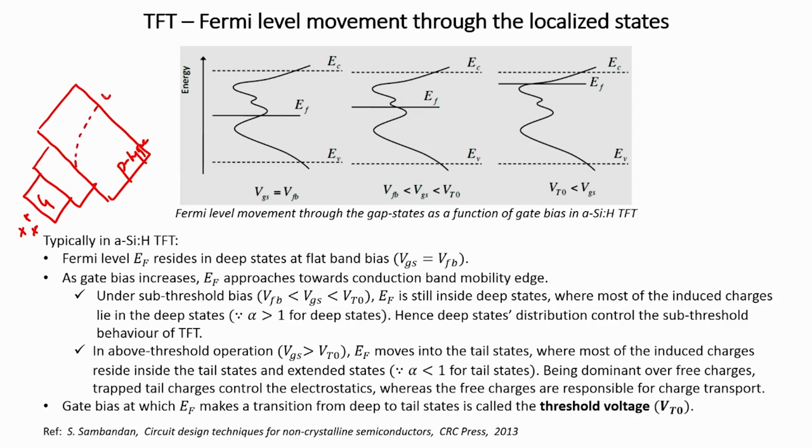The conduction band and valence band began to bend towards the Fermi level. We first achieved depletion wherein all the positive charge on the gate was compensated by the negatively charged acceptor like ions in the bulk.